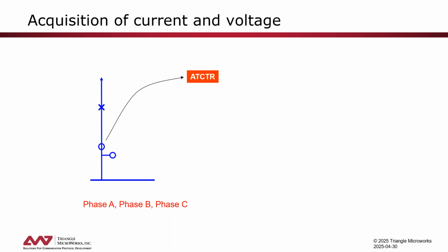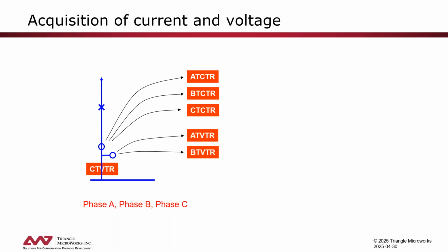This logical node is single-phased, so that means we have one instance per phase. So we have A, B, and C, so that's basically when we measure the currents of the three phases, we have these three logical nodes there. The same for measuring the voltage. The logical node there is called TVTR for voltage transformer. Again, we need one per phase.